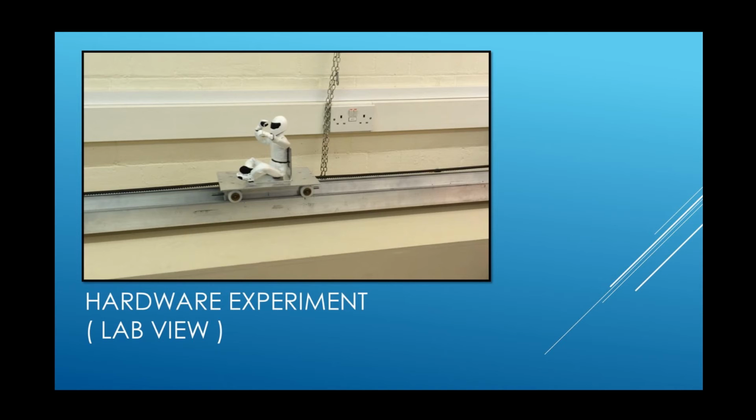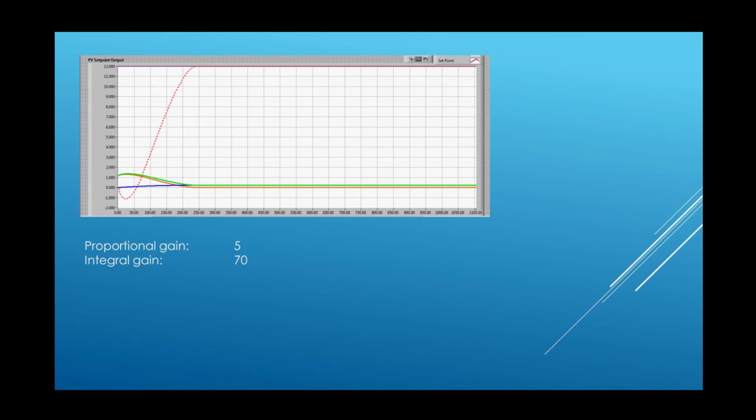By inputting the proportional gain and integral gain, the car will move along the rail. In the hardware experiment, the perfect response can be obtained when the proportional gain is 5 and the integral gain is 70. The following video shows the movement of the car when the parameters are 5 and 70.